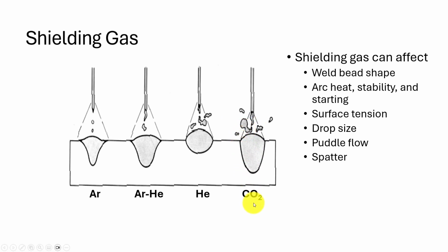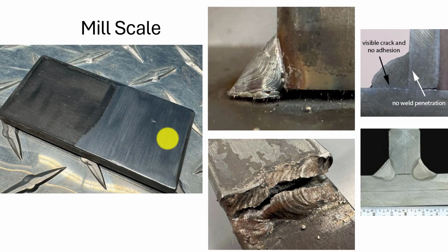But you're saying, why are you putting oxygen in there when we're trying to protect it from oxygen? This amount of oxygen in the CO2 is just enough to help promote arc growth and make a hotter weld. There's a lot to this stuff. Argon mix may be really good for better penetration and look a lot better, and not require a lot of cleanup from the splatter. Now, before we weld a piece of material, let's talk about our base materials.